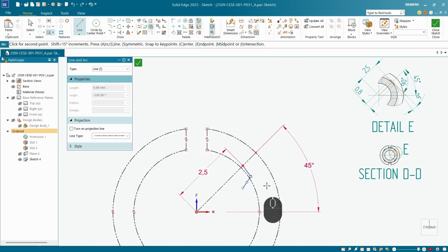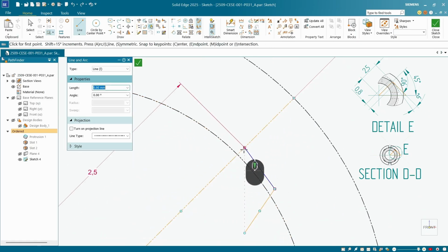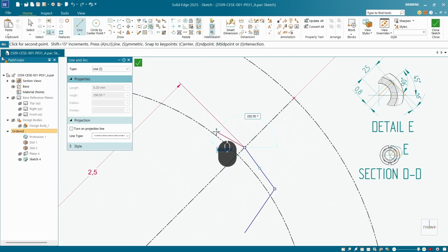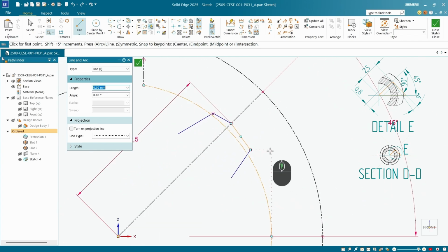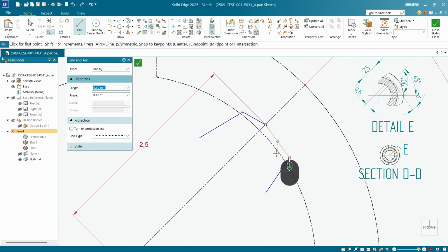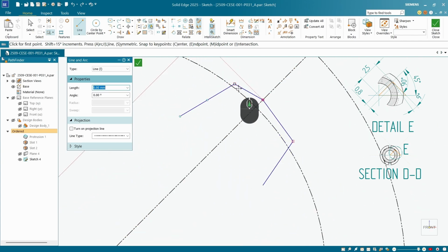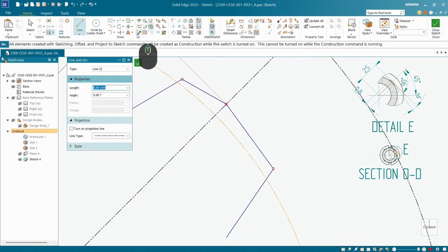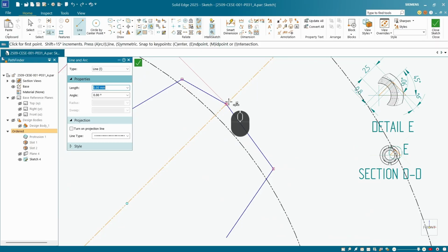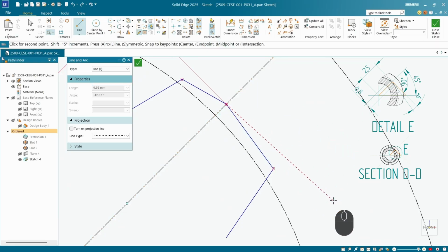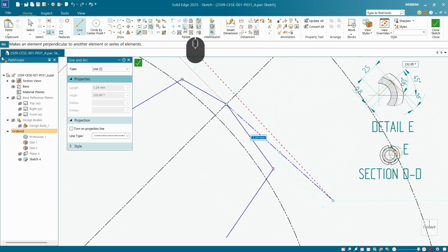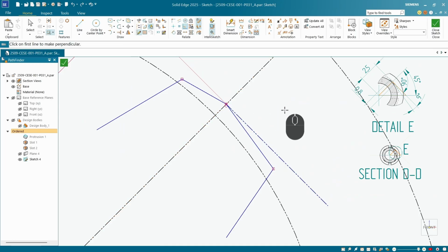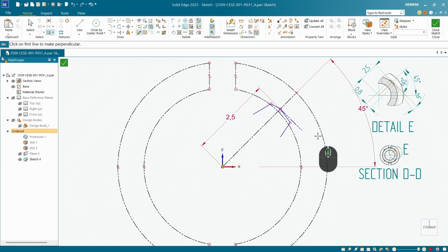draw back in again here and right click, and we can do the same on the other side. I'm careful not to automatically create a constraint I didn't want. Okay, so they look okay. It's obviously kind of wrong, but I did it wrong to prevent any accidental relationships getting created. And I'm going to create a construction line from this point out, and I'm going to make that perpendicular to this line. So this is at 45 degrees.